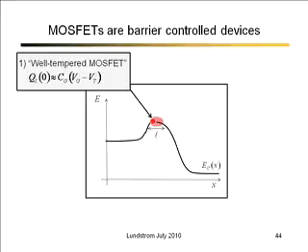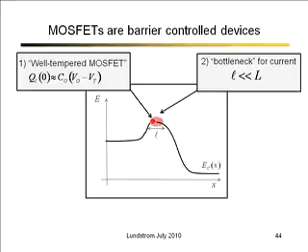That's why you start hearing more and more discussion of double gate devices, nanowire devices. It's all an attempt to control the electrostatics and control that potential by the gate and not by the drain voltage. There is this short bottleneck region. That's really the important region for determining the on current.